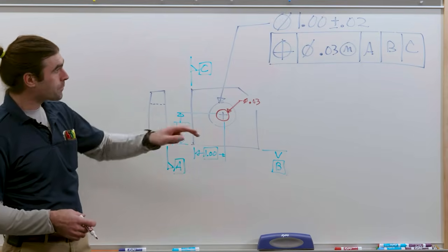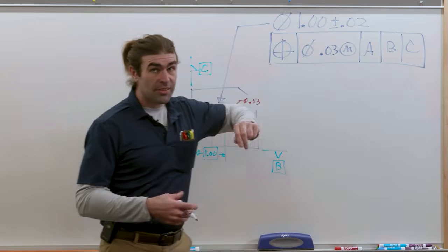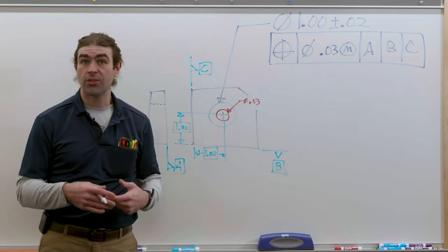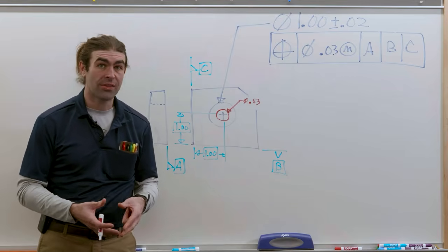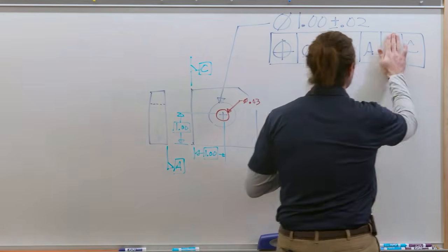Doesn't have to be. The second one is our secondary datum, typically the second largest surface, but it can be other kinds of features as well. It could be a feature of size, like a slot or a cylinder. So we could switch this.